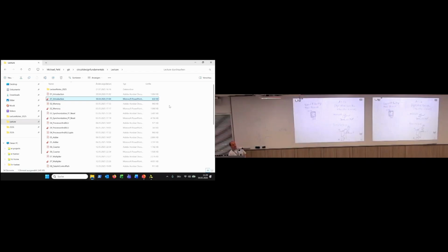A, obviously, everything is connected. B, obviously, everything is connected. So we can just have two stripes of connection material. How long should I draw this? Maybe a little bit longer. One of them is A, the other one is B. And this, just to give a little legend here, is usually done in polysilicon. Just connecting material. The lowest level usually is polysilicon, and that's what we use for here.